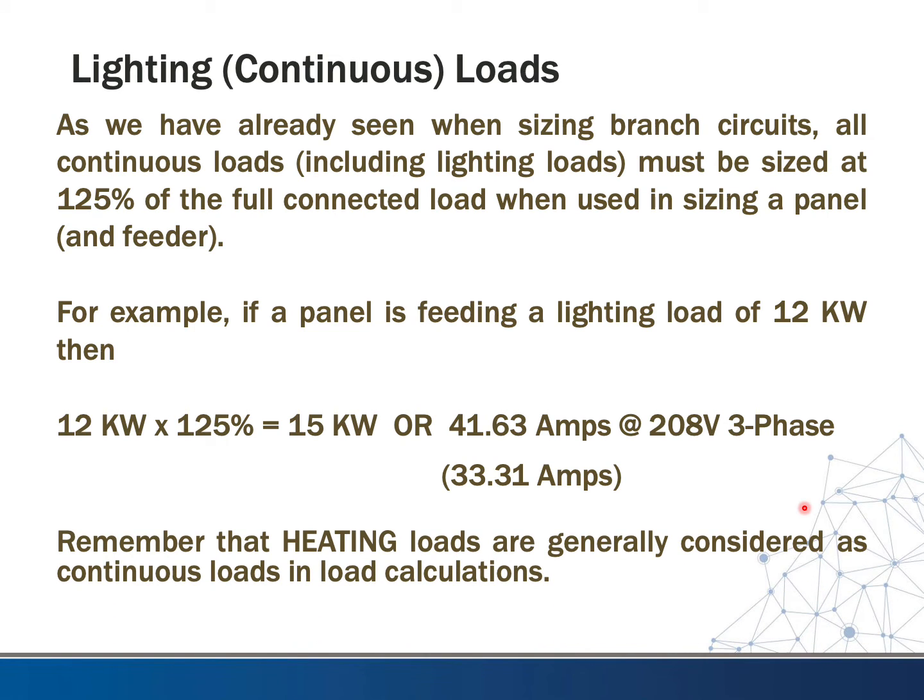Again, we need to remember that heating loads are generally considered as continuous loads in load calculations. So this can vary though. If you live up north, the heat definitely could be expected to run for more than 3 hours at a time. If you're down in the south, like in Mississippi, Georgia, Florida areas, that may not be the case. Your heat may not run that long. You might not expect it to in normal conditions. So I've actually seen this counted both ways. I've seen heating counted as continuous up north and not as continuous in the south.